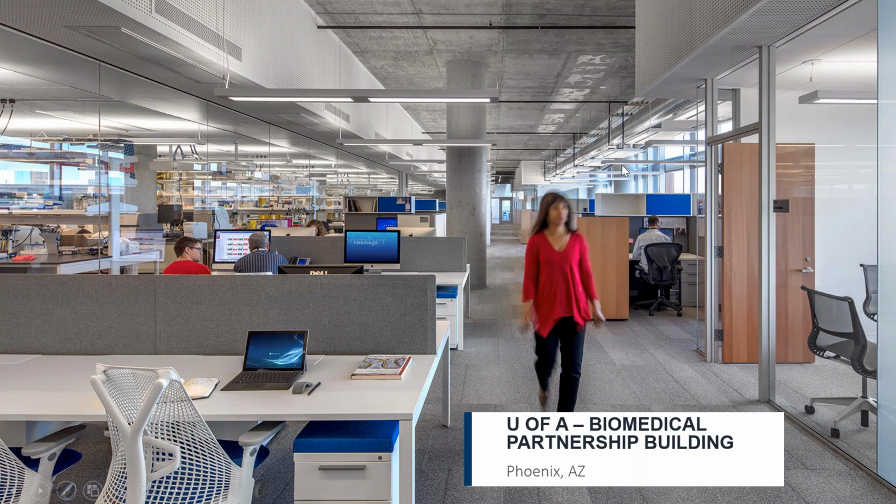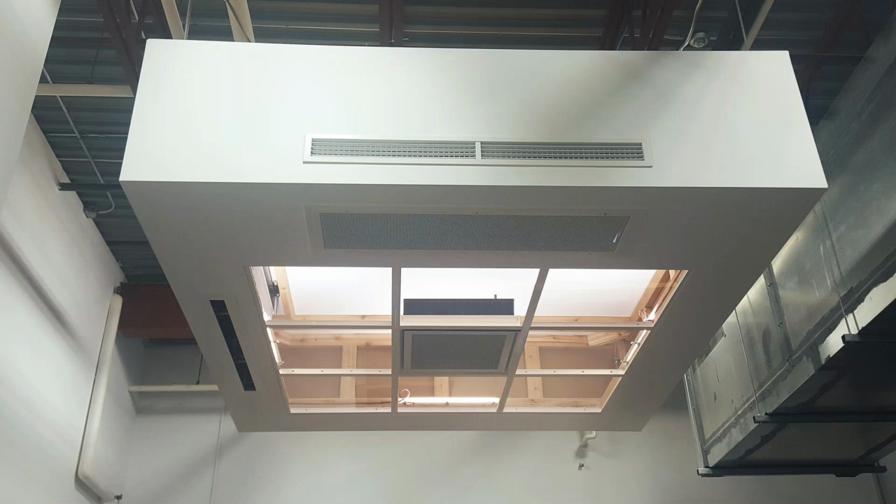It's a bit harder to see. Hopefully, being at the computer screen, you can see the exposed linear beams with the Coanda wing option. So you can add wings, even if in most cases we're installing the linear beams flush within a T-bar ceiling. So you have that horizontal surface for the air to hug against and create the Coanda effect. But if you have an exposed style approach, you can introduce the option of the wings to help keep the throw horizontal in an exposed application.